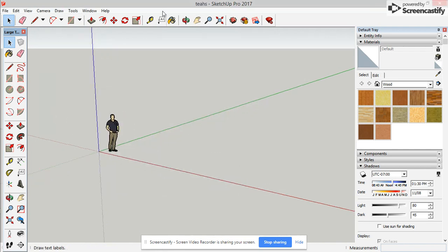Now we're going to start with the base, just like the Farnsworth House. We'll start with the base somewhere over here. This time, since it's meters, we don't have to put feet or inches, anything. You just type in the numbers. It's all meters. So we're going to say 4.2, comma, 3.2. Enter. There's the base.